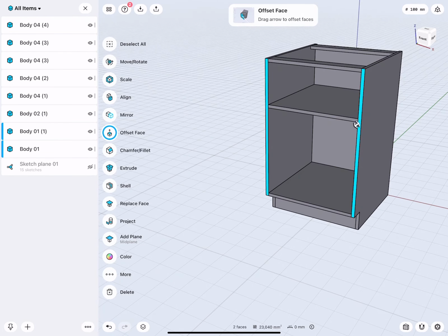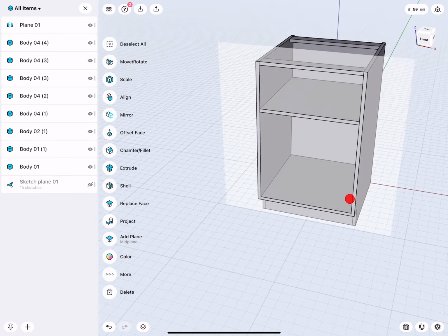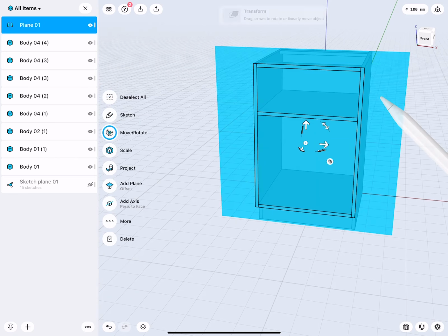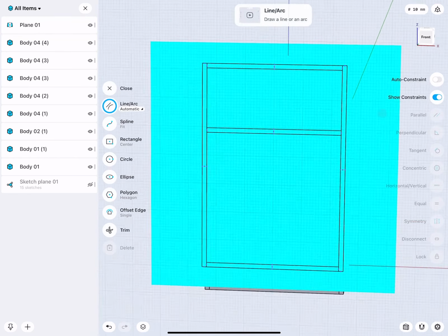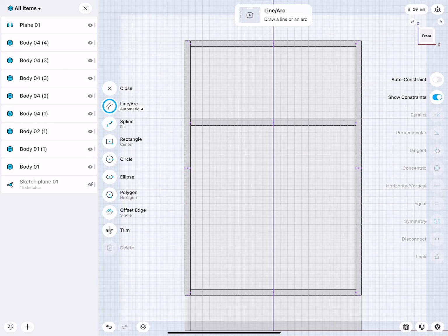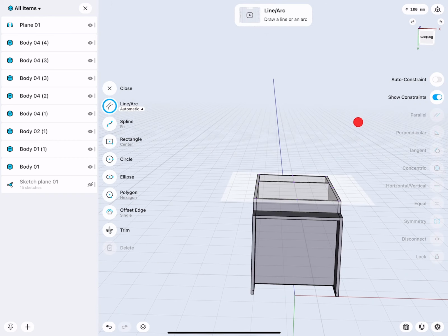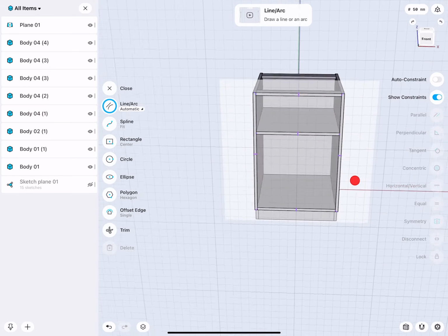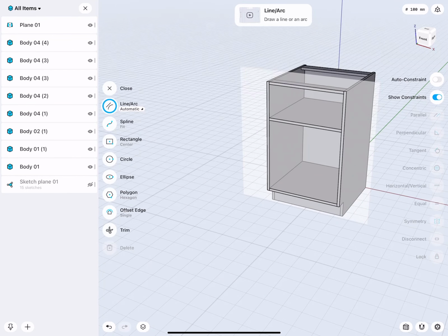And then we could, for example, add construction plane and put that plane right onto it. When I select this plane and double tap, everything actually moves right to it. So you see we're actually looking right onto that sketch. Or sorry, not sketch. The grid got projected to the construction grid.